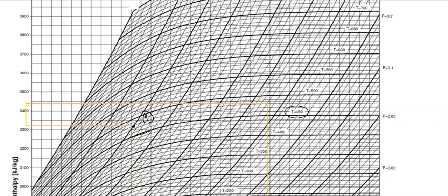For simplicity of this lecture, I've already drawn these lines on an HS diagram using different colors. But yes, I would explain it anyway. So this is 10 megapascal and 480 degrees centigrade. So now checking the enthalpy over here.